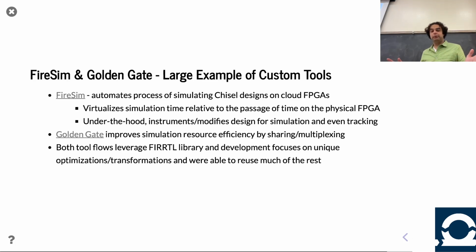How do you split it across multiple FPGAs? That's a challenge. Number two, what do you do if your FPGA is running at 100 megahertz, which is pretty good for FPGA, and the memory it's talking to is running at real memory speeds? Now all of a sudden the memory in the simulation is running at incompatible speeds compared to the real world.